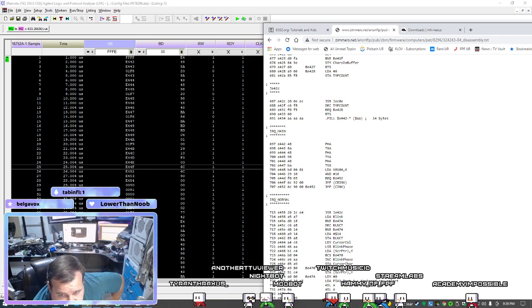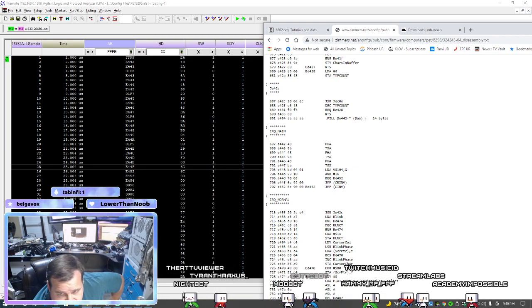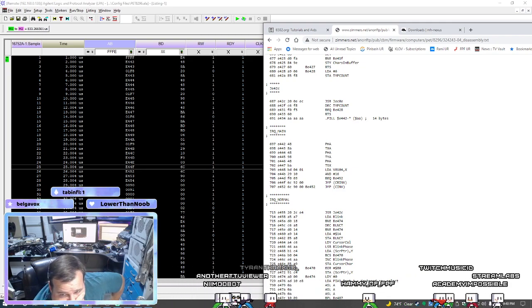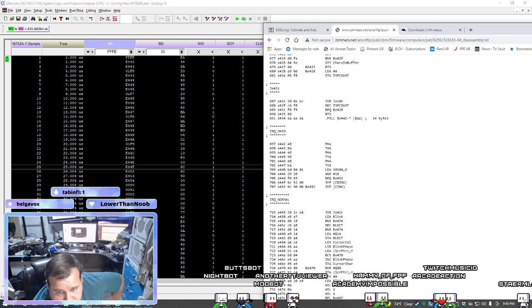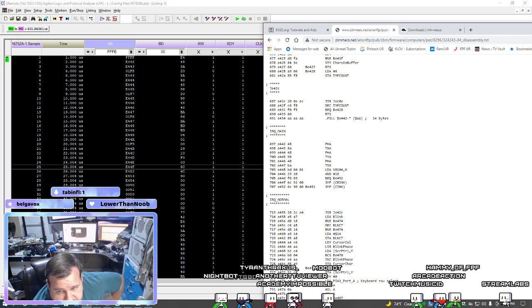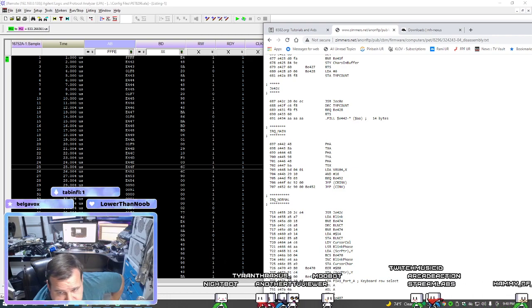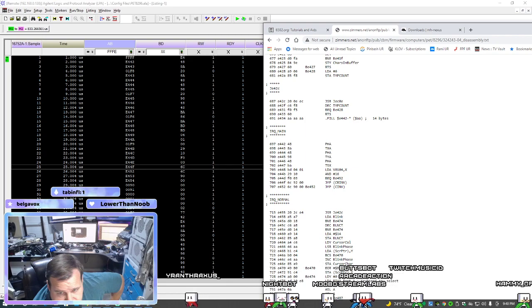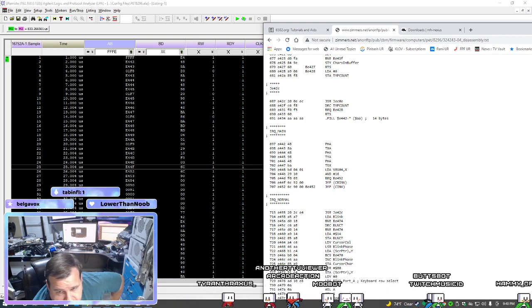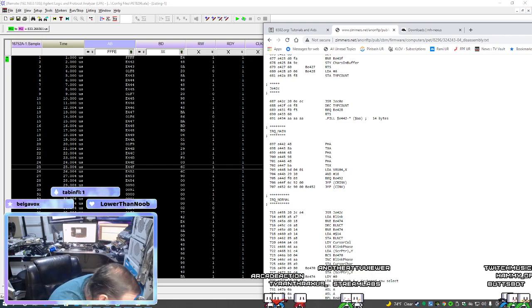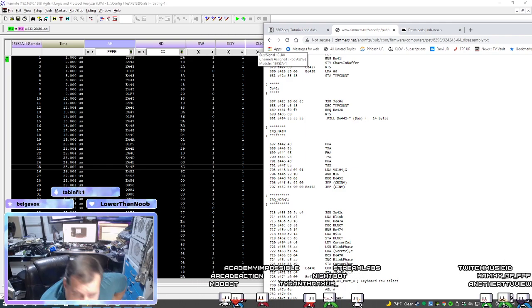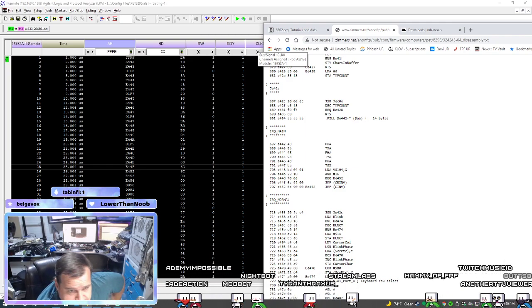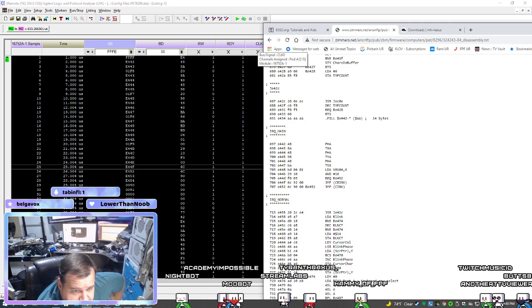Then it should jump to the branch if equal to E452. Otherwise, it's either going to block to jump to 9000 or 9200. 9000 and 9200 is an option 10 socket. I don't have anything in the option 10 socket. It's not even jumping there.